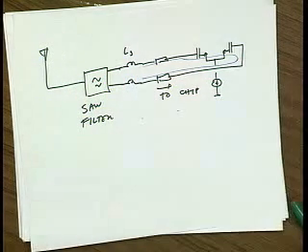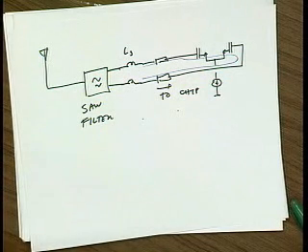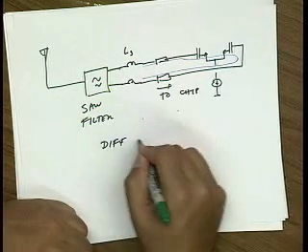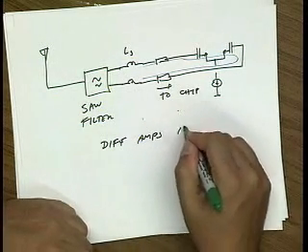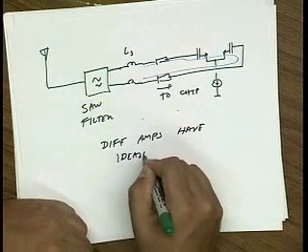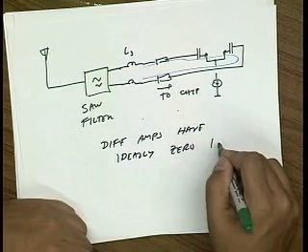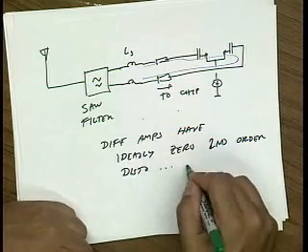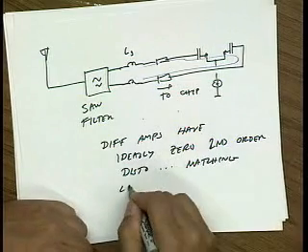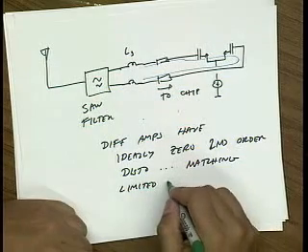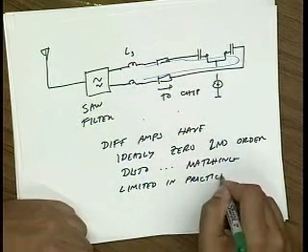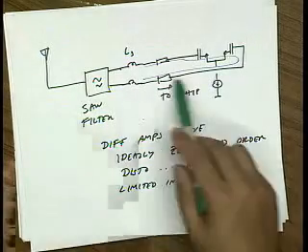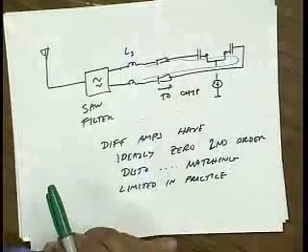One thing that you guys have learned about is differential amplifiers have much lower IP2, right? So differential amplifiers have ideally 0 second order distortion. Otherwise, it's matching limited. And that was a bonus problem for you guys. Nevertheless, if we make these transistors fairly large and we're careful about our layout, we can get pretty good matching and therefore very good IP2.